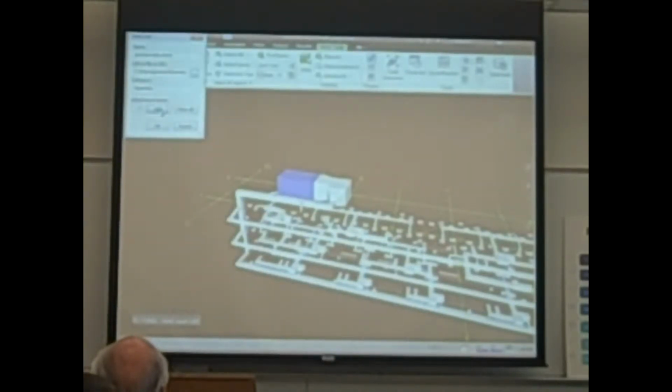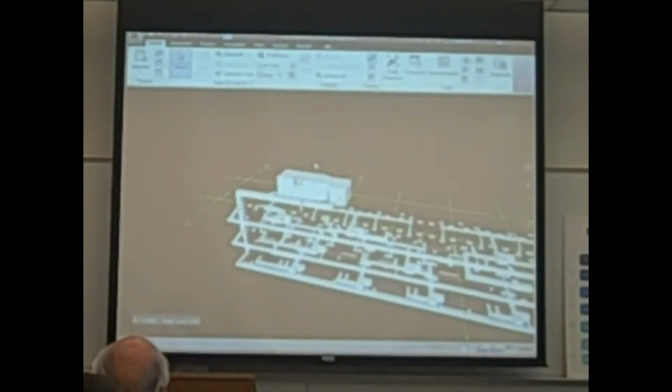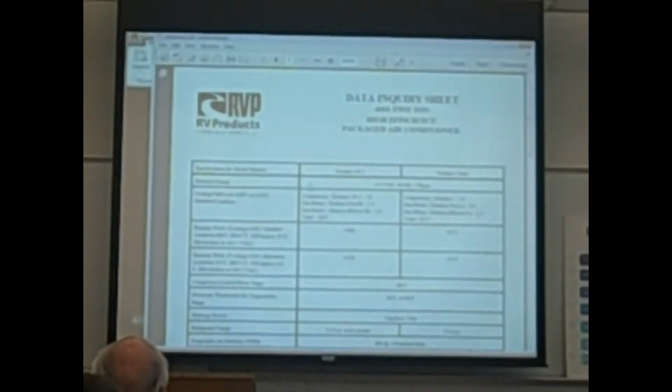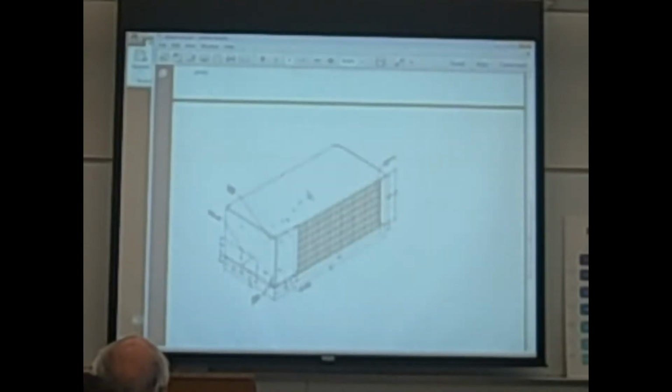Let's say I've got a document here, a little PDF that I want to attach, and then I want to give it some sort of a place inside of the model. So now if somebody has this Navisworks file on the owner side, eventually they'll be able to come in here and see all these various locations where we've placed links, and link to that set of information. So, did that PDF actually get embedded into the file, or is it just a link? It's a link. So you have to have this be its own self-contained package. Otherwise, your system is different than my system, and all these things are sort of broken.